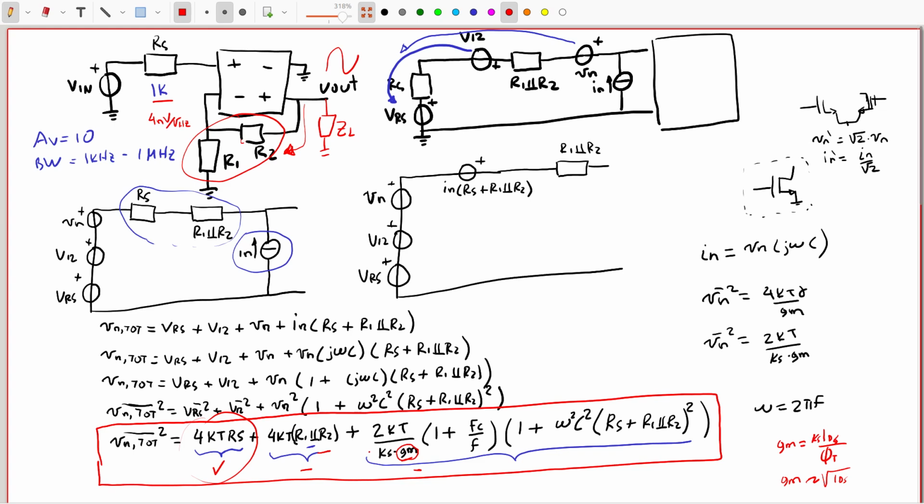Sometimes I can tolerate more noise. As mentioned before, it depends on the signal to noise ratio that my system can tolerate. The signal to noise ratio will be mapped to an analog to digital converter, the quantization, also the digital to analog converter, and then that will set the noise floor that I can have. But since we don't have those characteristics of that information right now, we are just going to assume that